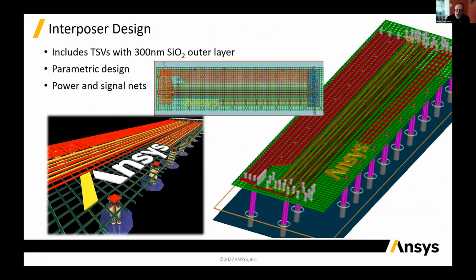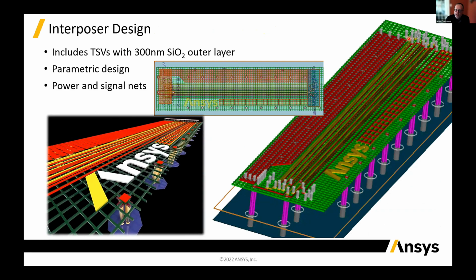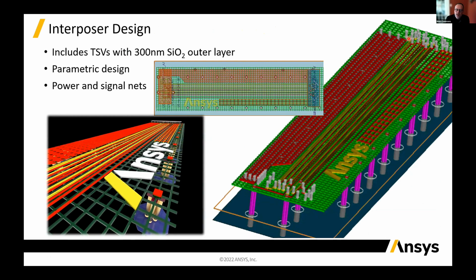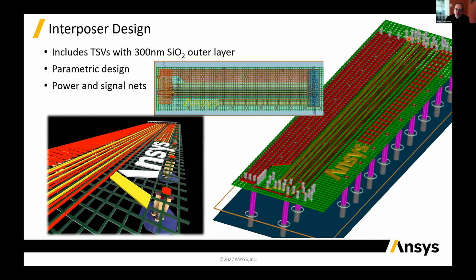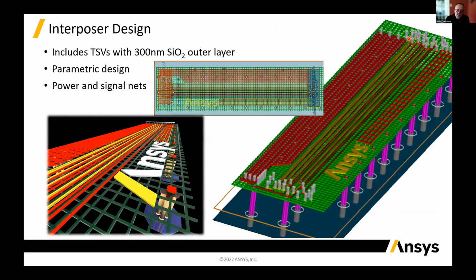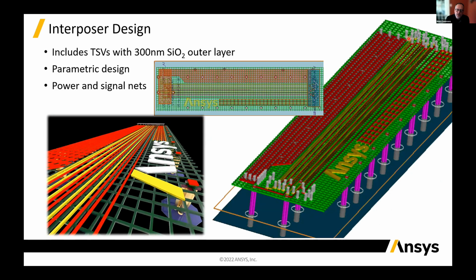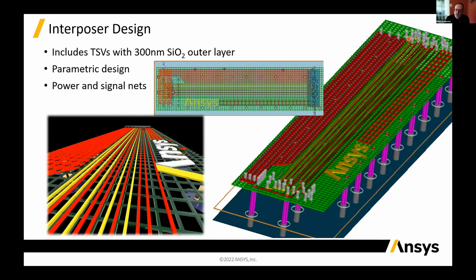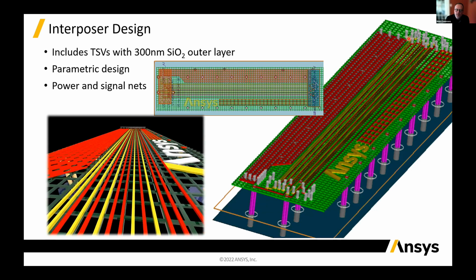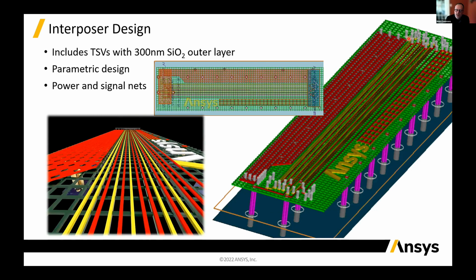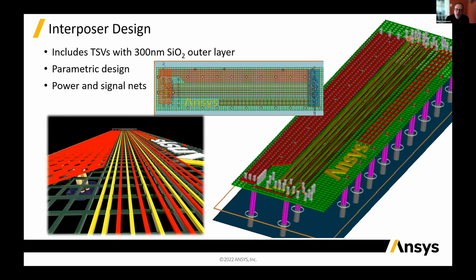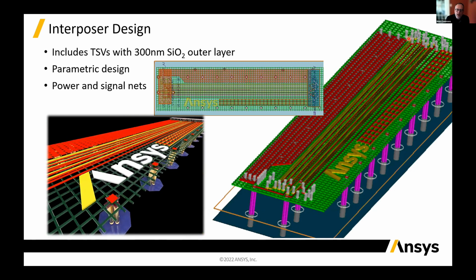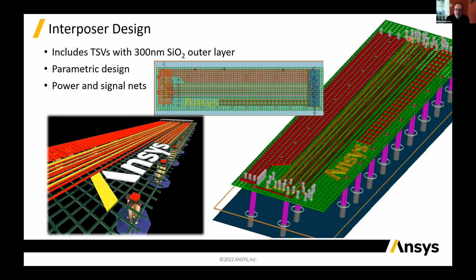So specific to interposers, as Kelly's already mentioned, the CAD can be extraordinarily complex. That's probably one of the most significant differences that we might see in terms of this newest packaging technology versus, say, organic packaging from 10 years ago or so. And so they're challenging. To achieve the discretization takes a lot of mesh elements. Meshing alone can be challenging, but we can tackle these fairly complex interposer designs. Here's an example of an interposer design that includes the through silicon vias on the bottom layers. Next slide, please.